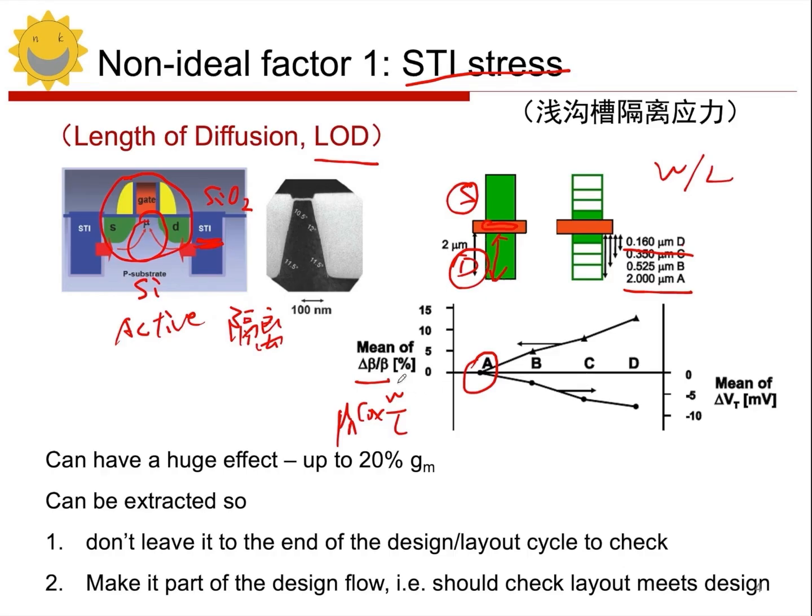The deviation between the beta parameter and the predicted voltage parameter is a gradual change from small to large. In this case, we will find that the area of the original leakage region is larger, and the deviation of the parameters of this transistor will be smaller, right? It has such a characteristic. So what is the reason? The reason is this STI stress problem, right?